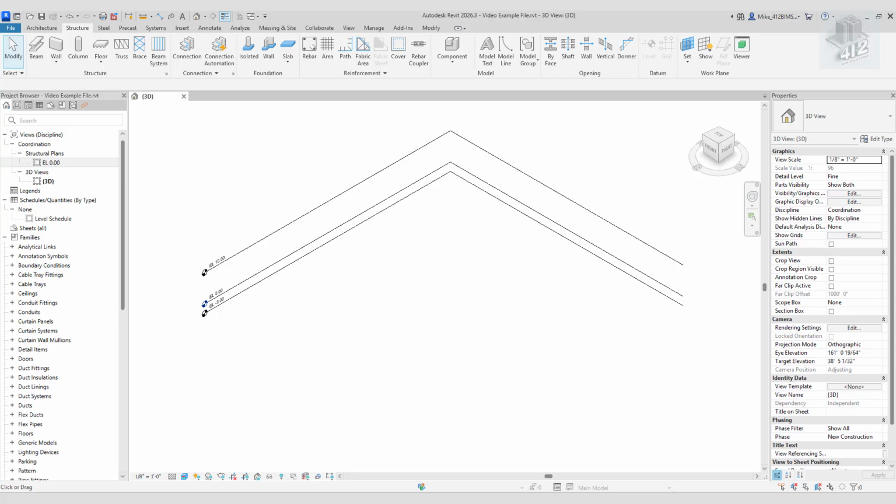They don't even prompt you. The one key difference, though, is that with Transfer Project Standards, they will overwrite your existing types in your destination file if they share the same name. The copy-paste method will not overwrite. Instead, it appends the incoming type to have a 1 as a suffix, which in time can cause clutter and potentially confusion in your project file.